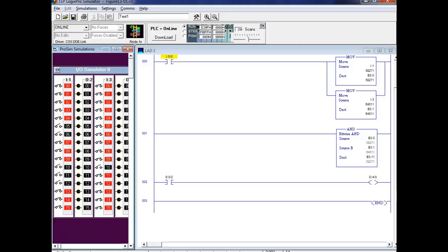So these single bits are these status registers. If you wanted to do something if you had a carry, if you want to do something if you had an overflow, if you want to do something if the number was negative, you have to program it in, right? You understand? But just like when we used that S2:14 or whatever it was, that bit's been up there flashing the whole time. But it was never used until what? Until you assigned it and you said, okay, this is what I want to do on that.